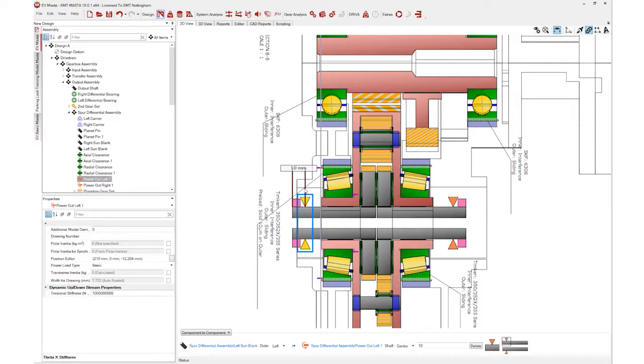And if I click on my two output power loads, so the ones I've got on my half shaft here, you will notice in the properties list there is an upstream and downstream inertia properties. Now this is a simple value you put in, which does allow you to just simulate that downstream properties and will allow you to get, or hopefully get you a bit more of a realistic correlation. So it's all these little bits of modeling detail that you could put in there just to help you towards getting an accurate model in comparison to your test data.